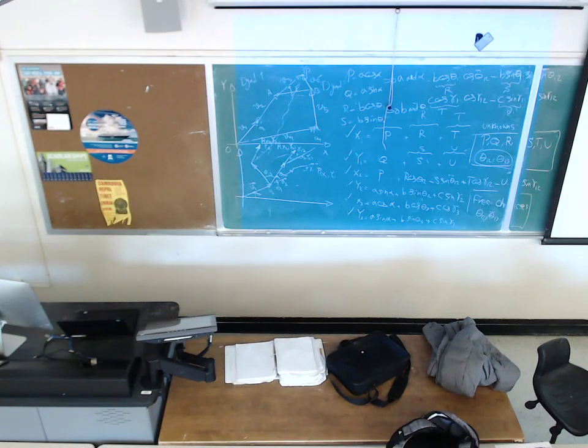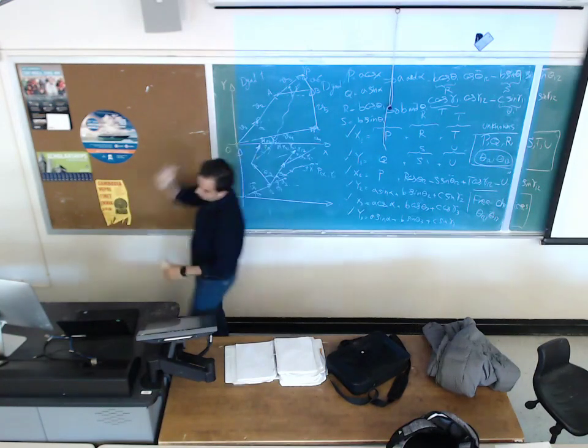You know theta 1, you know B, you can find the location of A. You know gamma 1, you know C, you will find the location of point P. This is vector V1, V2, V3. So we are done with the first half of the mechanism, or first with diad 1.